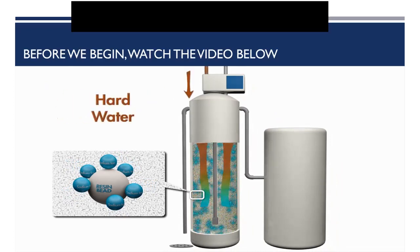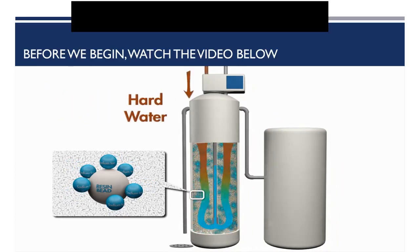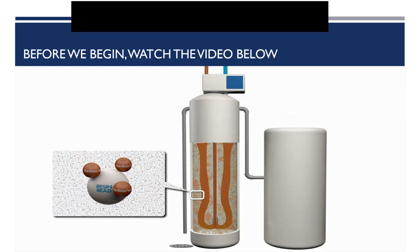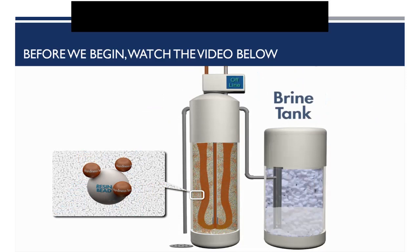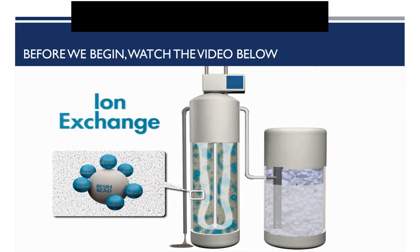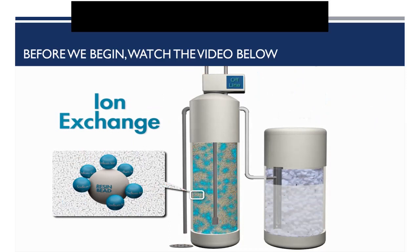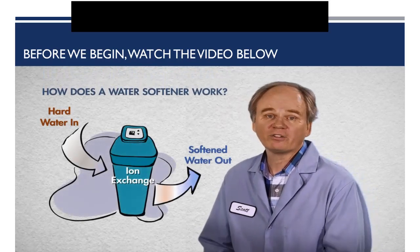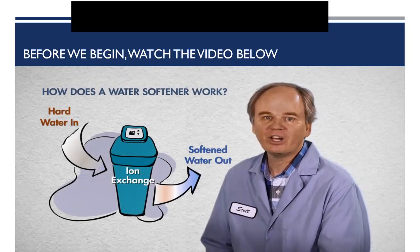The water softener pumps hard water through this bed of resin beads, and the hardness ions are exchanged with the sodium ions. Now, eventually that resin will fill up with hardness ions and it can't soften any more water. At that point, the water softener must regenerate. The water softener goes offline, and this is where the brine tank comes in. Salt brine from the brine tank is pumped into the resin, and that salt brine washes away the hardness ions and replaces them with a fresh layer of sodium ions, so the softener can then go back online and resume softening more water. So I hope this has helped you better understand how water softeners work. If you've got more questions, please let us know.